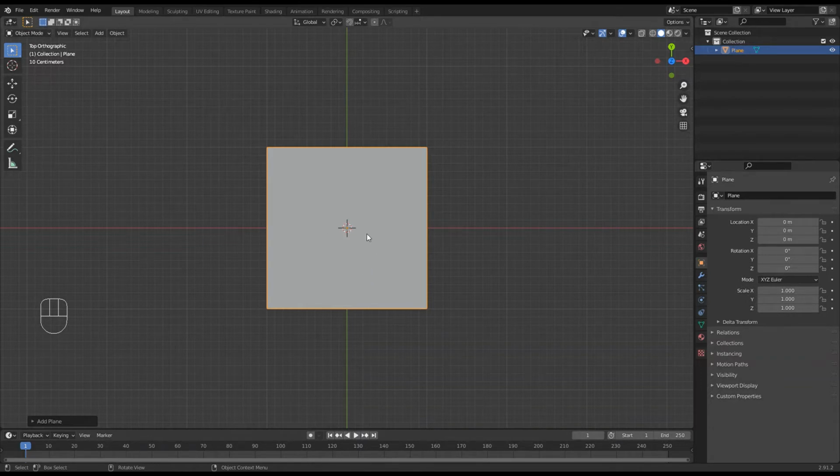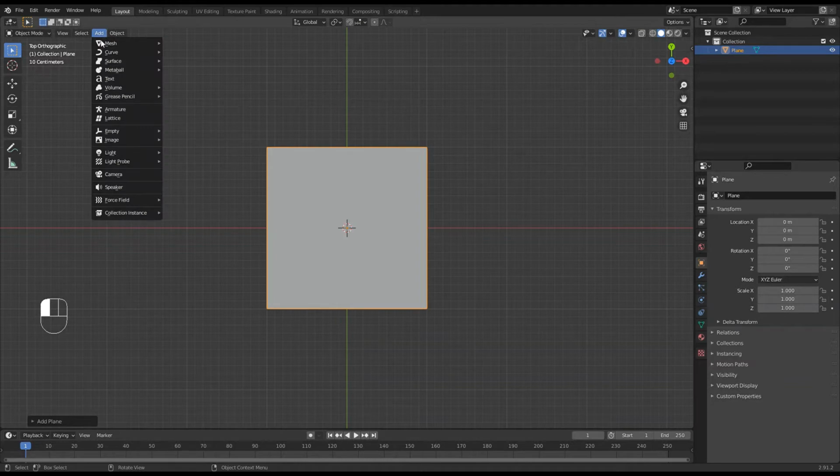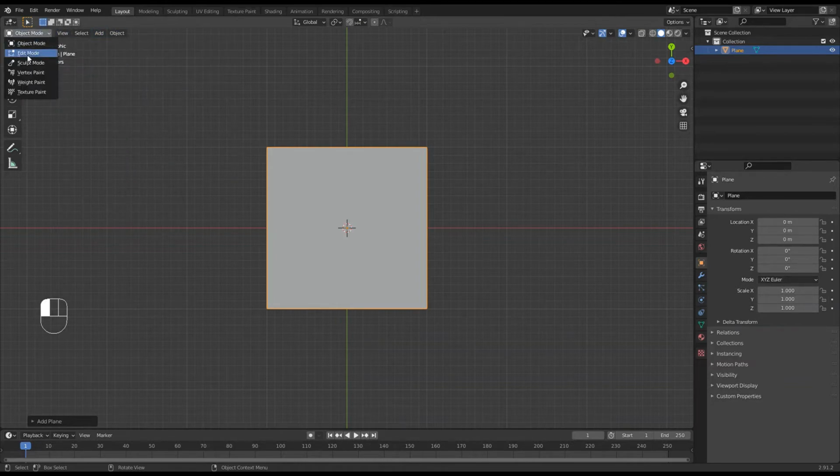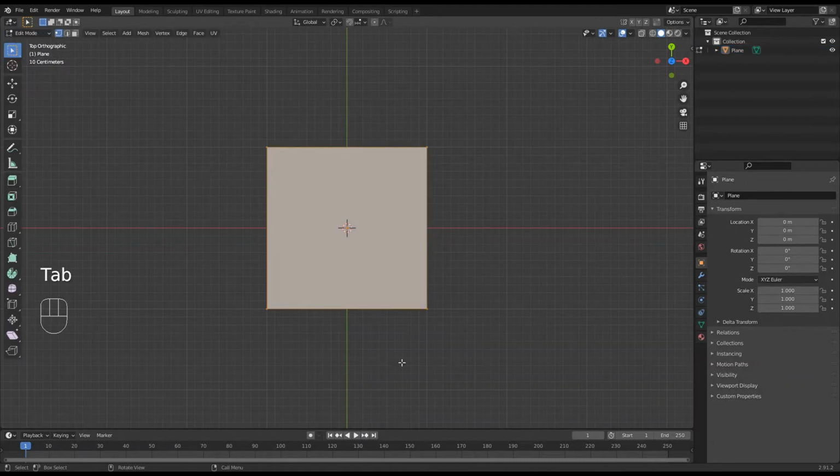Okay. Now I want to start editing this preset plane. I'm in object mode. All your adding of materials gets done in object mode. And now we'll go into edit mode, and the Tab key will do that. So enter Tab. I select one of the little dots, and these dots are called vertices. Now I just want to retain that one, so I want to delete the other three, but obviously you would delete what is selected. Control I is to invert the selection, so now the other three are selected.